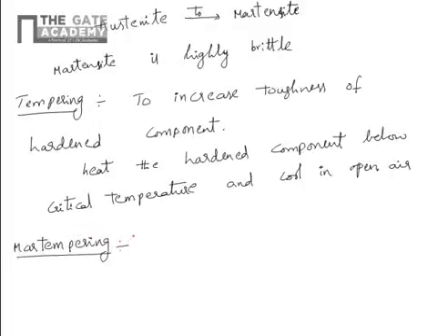Martempering is also called stepped quenching. Heat the material above critical temperature and quench it to just above the martensite temperature, and then cool slowly.